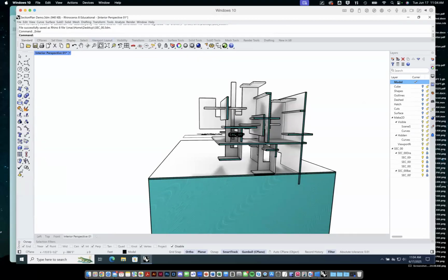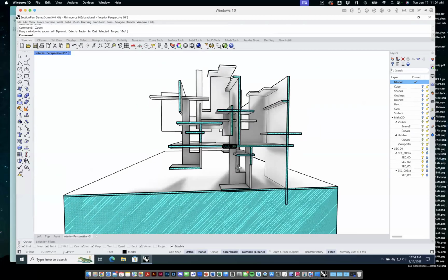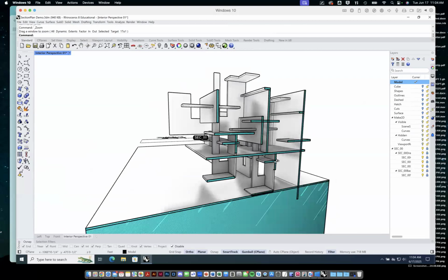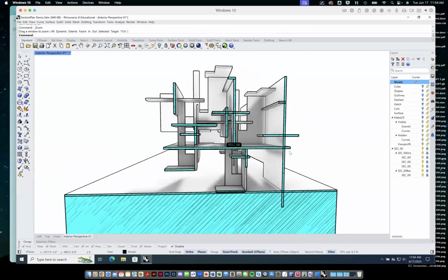Let's get started, right? What's interesting is that when I start to read this, I go, well, first of all, there's a lot of science fiction here. That's a dramatic cantilever that wouldn't work. The horizontal surfaces, if people are going to be walking on them, there are live loads and dead loads on them. They need to be a lot thicker than the walls. And then we also need basic supports. I would try to bring some of these surfaces down to the ground.